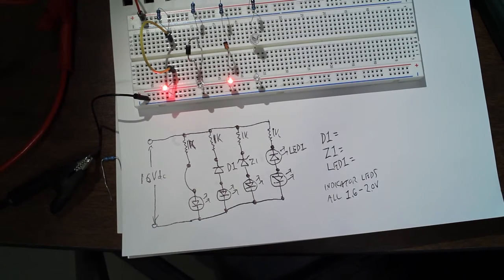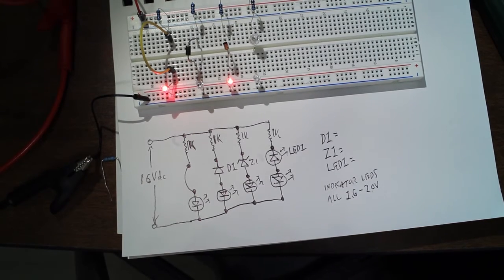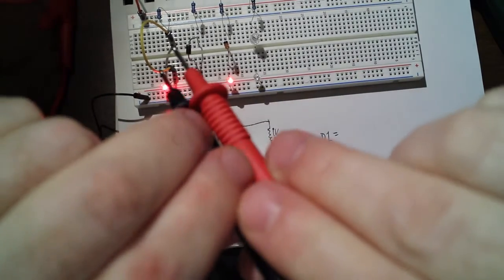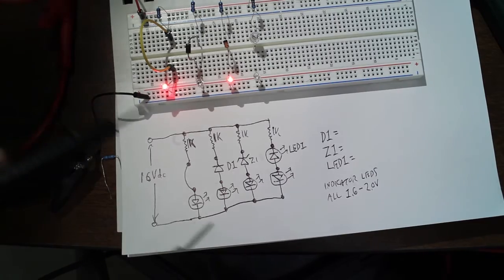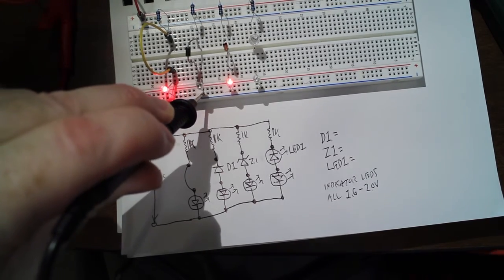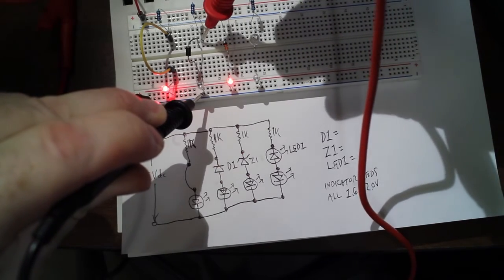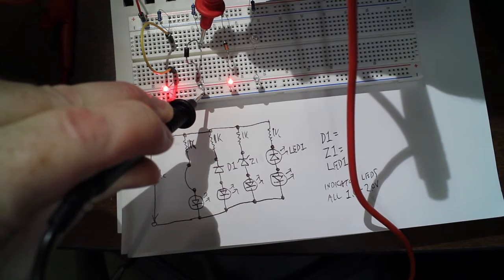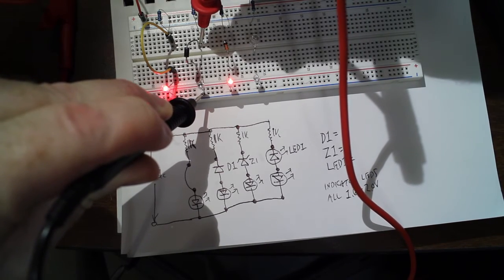Now, measuring these voltages is going to be a little tricky, because if you have zero current flowing through a circuit and you try and measure it with a standard multimeter, the multimeter's internal resistance will cause weird values. So rather than just going across the rectifier diode, I'm going to check the voltage across everything except for the resistor. So the rectifier diode plus the LED is 15.6 volts.